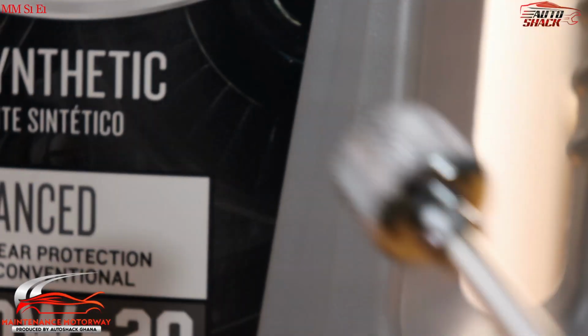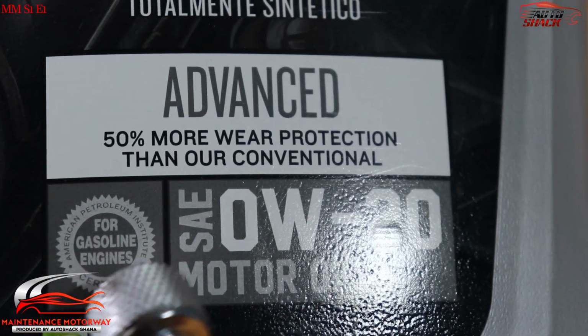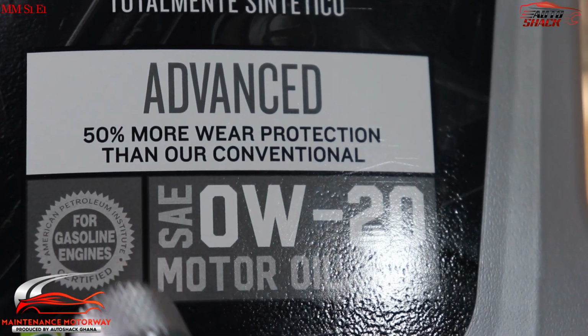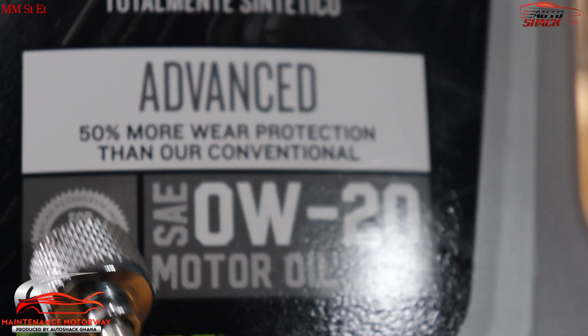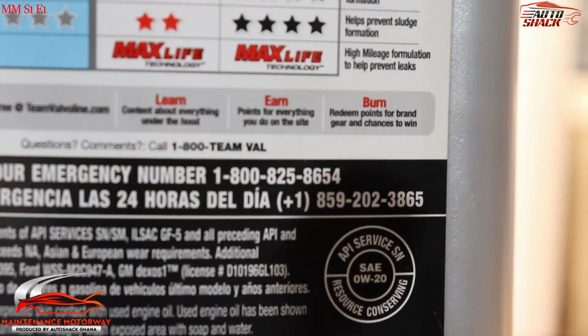For this one, for instance, when you look at it, it says for gasoline engines only, which tells you that this is not fit for consumption of a diesel engine. If you put this on a diesel engine, it's not going to provide adequate protection for your diesel engine, okay? So you shouldn't do that. That's why it's extremely important that you check these things.